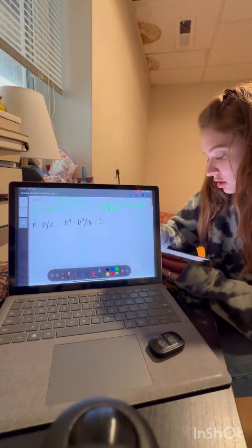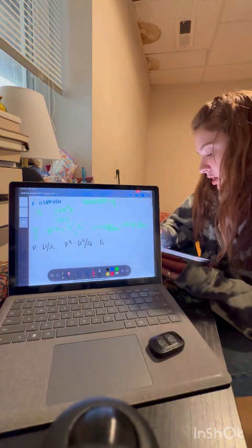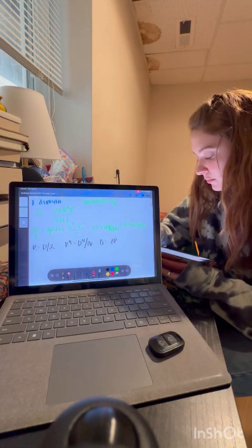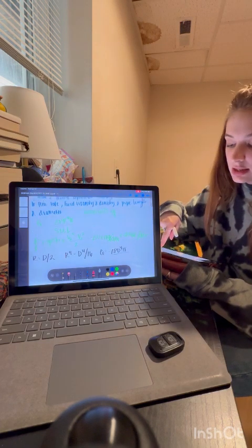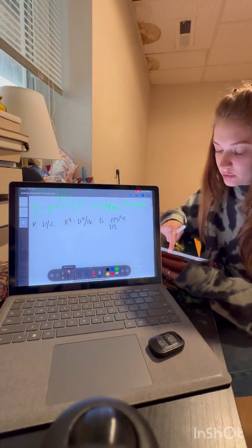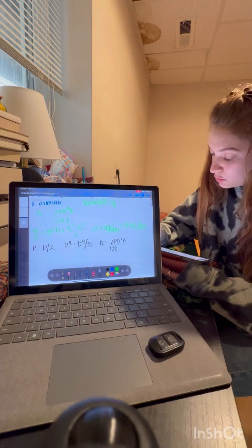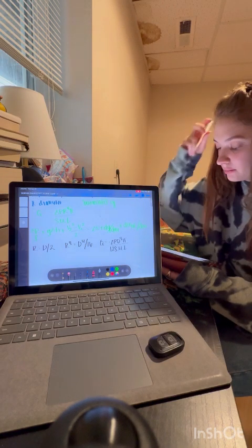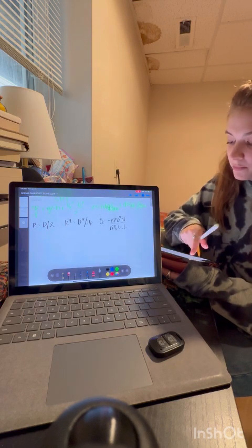That is going to be Q equal to a negative change in pressure times d to the fourth times pi all over 8 times 16, which equals 128, times mu times length. Make sure that negative sign can be seen.